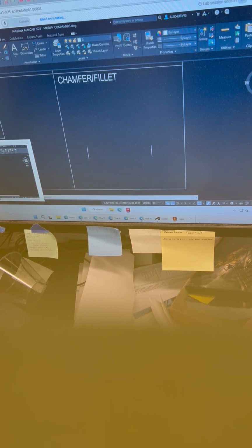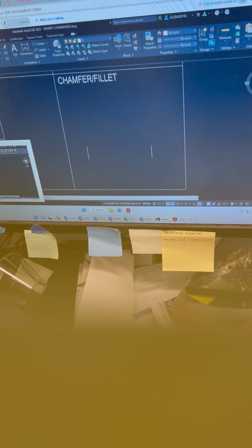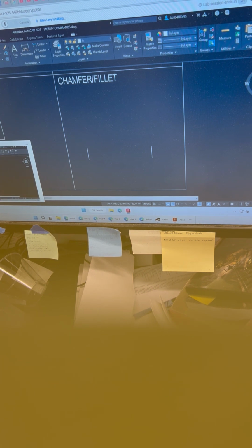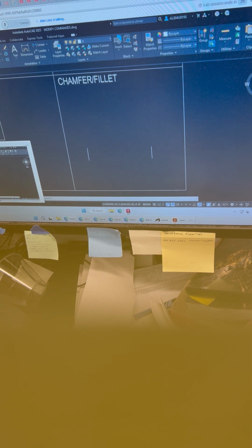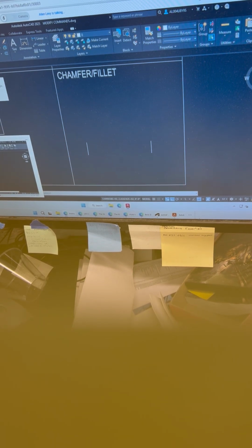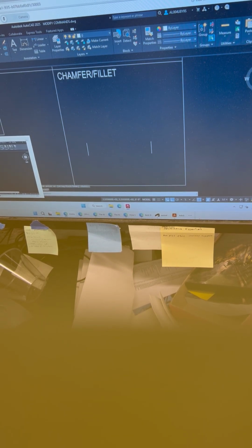All right, here's what I want you to do now. Start the same tool, polygon. Look how 5 is the default. You can just hit enter. You don't have to enter it in again. Just hit enter on your keyboard. Pick the bottom of this line as the center of your polygon. Okay? And then this time you're going to select circumscribe, about a circle.